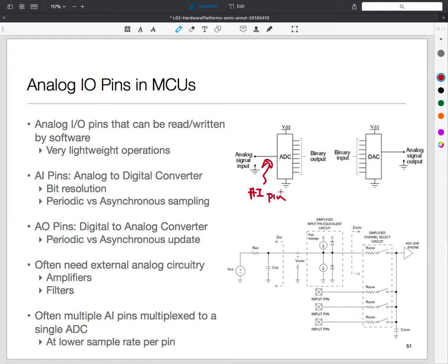So just to give you perspective, let's say you are monitoring something very subtle, very sensitive, I don't know, like vibrations of earth, the seismometer. You may need 20 bits, 22 bits. Just to put in perspective, 20 bits is 1 part in a billion, something like that, right? So very, very tiny signals that you are trying to transmit.